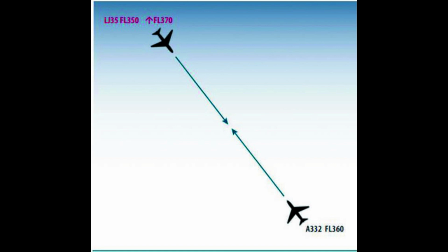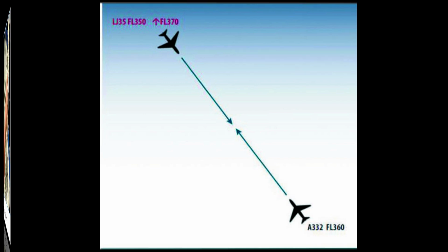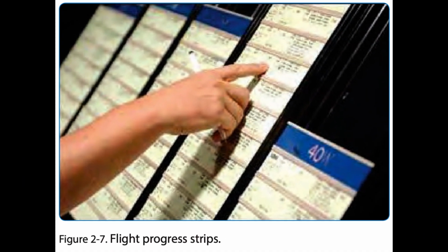En route control is handled by pinpointing aircraft positions through the use of flight progress strips. These strips are pieces of printed paper containing pertinent information extracted from the pilot's flight plan. These strips are printed 20 minutes prior to an aircraft reaching each center's sector. A flight progress strip tells the controller everything needed to direct that aircraft.